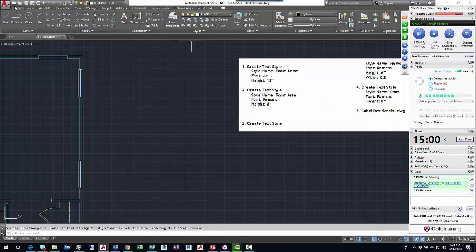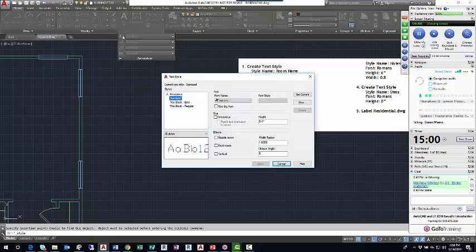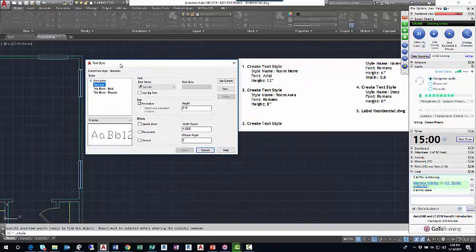All right, so I'm on the Home tab of the ribbon, expanding the annotation panel. Going to click the A with a paintbrush, that leftmost button at the top of the panel, left click. There will be a couple textiles already in here. Annotative and standard are just part of the template. They come with it, so we don't have to create all the text all the time. There's a couple pieces of text sitting there for us. Title block bold and title block regular came in when we inserted the title block. But none of these are really the textile I want to use for my drawing.